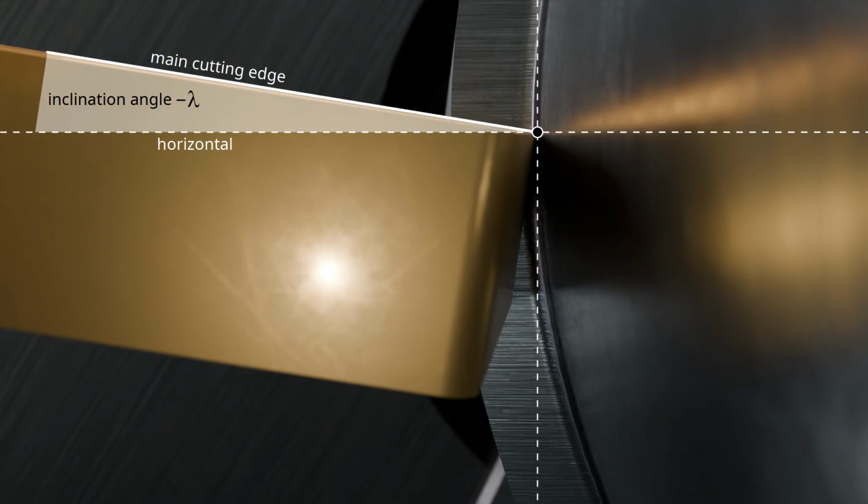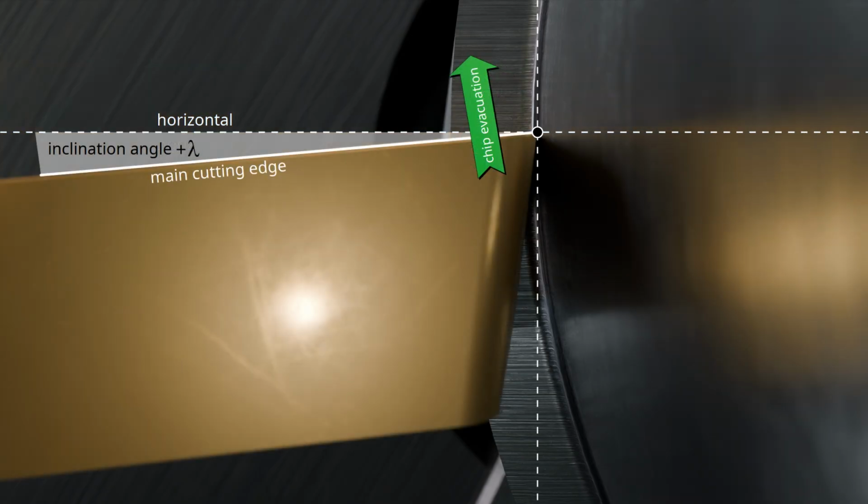Especially in heavy machining operations, such as roughing, a negative inclination angle in the range of -3 to -8 degrees is typically used. However, negative inclination angles are disadvantageous in finishing because the chip is directed by the rake face inclination toward the machine surface, which can cause damage. Therefore, a positive inclination angle is recommended for finishing, as it directs the chip away from the workpiece surface. A positive rake angle can also be beneficial when machining materials prone to adhesion.